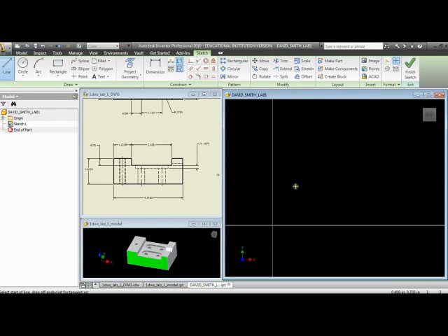With parametric solids, we don't have to be real particular about how and where we draw these lines. We're going to define that as we go along with something called constraints, which will tie things down and will control the attitude, if you will, whether it's parallel, perpendicular, horizontal, vertical, and so on. We'll also put parametric dimensions on it, and that will control the size of those particular features.